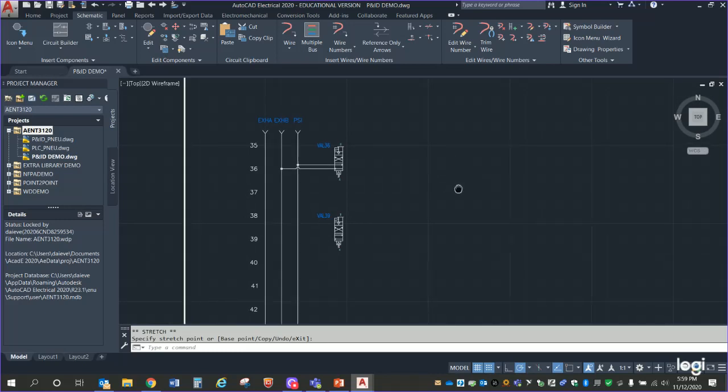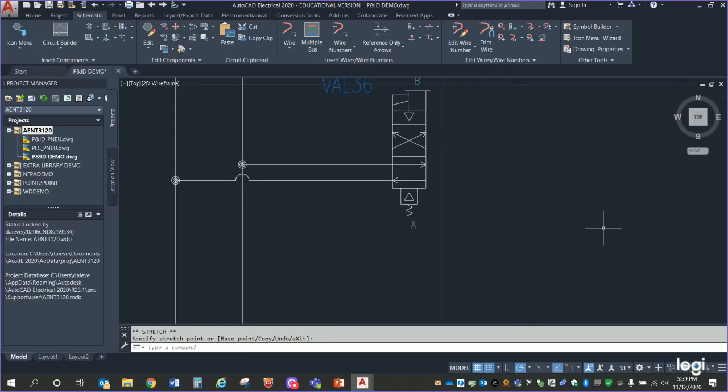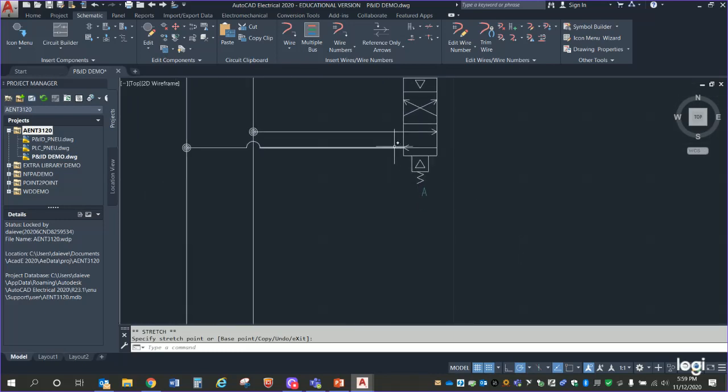A lot of times you'll see the mufflers actually sit right here, right on the outlet of that control valve. This is the same situation, right? It's just going to go through the pipe to the muffler instead of coming right out of the control valve. This might cost you more on tubing and less on mufflers, because I need fewer mufflers but more tubing.